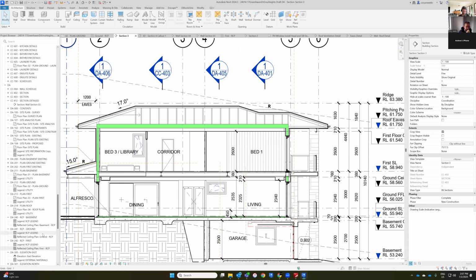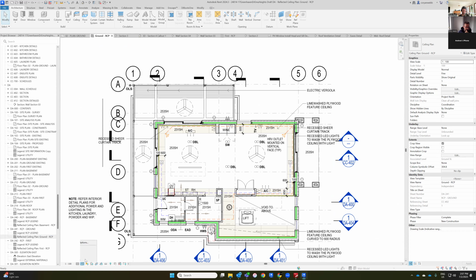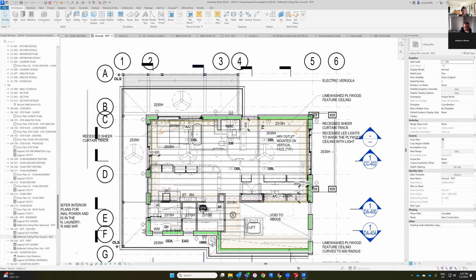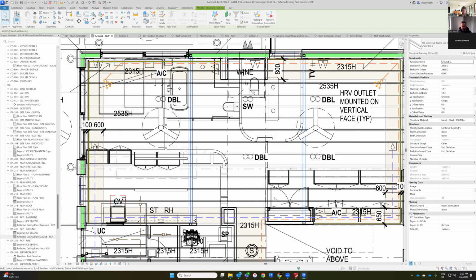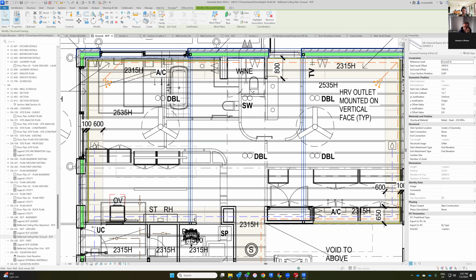Yeah, I've been having a look just to make sure that the position of the windows and doors and structurally everything works as well as it can. So I've put in all the joists and beams. There's going to be two main steel beams from the previous structural design with these columns here and here, column here and here, and then the joists spanning between there. So what are those columns made out of, Corey? Steel. So you've got a steel column in the building envelope. Yeah.